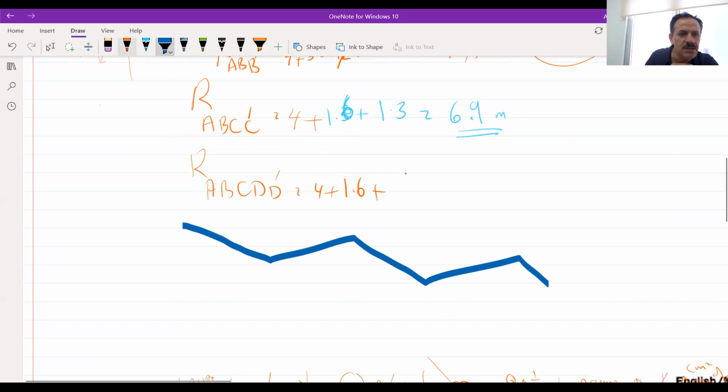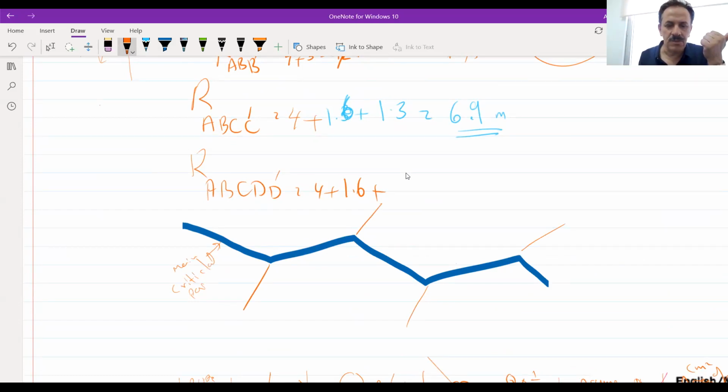This is the main, or critical, path, and then there will be branches. Unifying everything to one diameter will help you minimize the total head losses in the whole network, because this critical path is the one that affects the network.